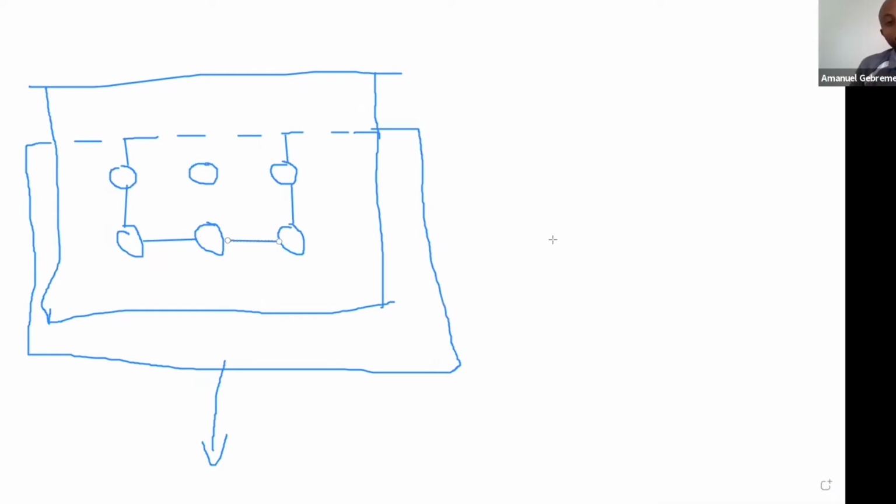Okay. So even those of us who design connections all the time have to think about these things very carefully. If I load this plate in this way, and I'm talking about this bottom plate now, a failure type that I might have is where this block of steel that I have just circumscribed with my straight lines can actually break out and fail.